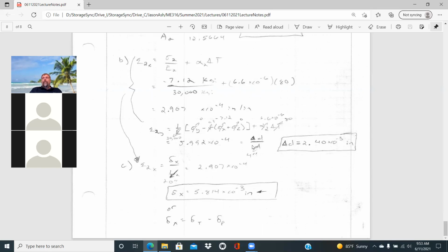And so when you do that analysis on the strain, that final diameter minus the original diameter, and place all your 2 pi's in there, or pi times diameter, all those pi's will cancel out and you'll be left with delta D over D. So circumference is pi times diameter, and all the pi's would just cancel out as you do that. So that gets you the change in diameter.